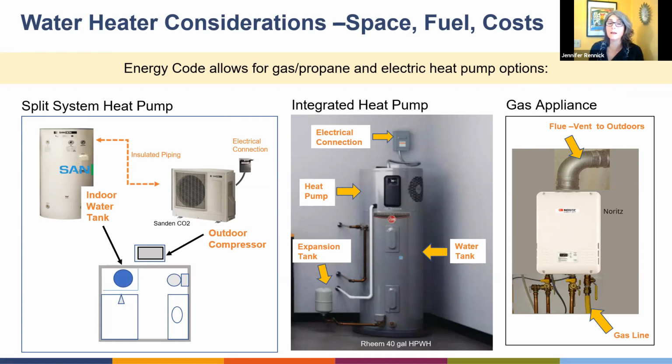But keep in mind, you need to plan for it ahead of time, because you don't want to be out of hot water for a long time if you're waiting to have an electrician come out to run the electrical so the plumber can come and finish it. But you can also see from that middle picture, the plumbing itself is really, really straightforward. And in fact, it's easier than a gas unit because there's no gas line to run or to worry about at all. You have incoming cold water at the bottom of the tank that plumbs up really easy.